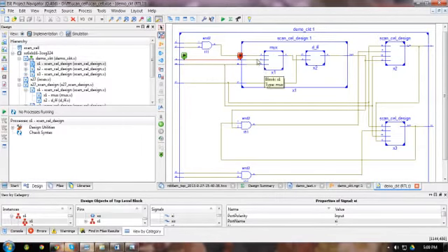And this mux has two inputs, one directly coming from the AND gate and another coming from an input called the scan input, which is here. In order to select either the input from the AND gate or the input from the scan input, which is one of the primary inputs, there is a select line. This is a select line as you can see. When it is 1, it will take the input from the scan input, and when it is 0 it will take the input from the normal AND gate.